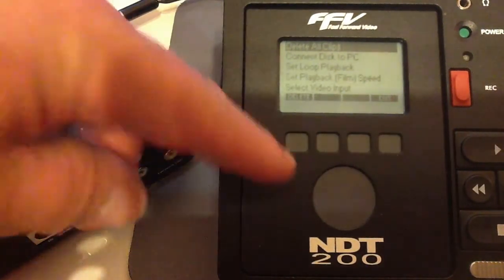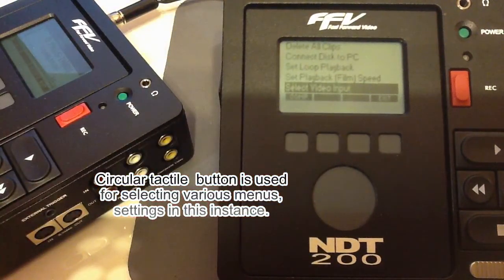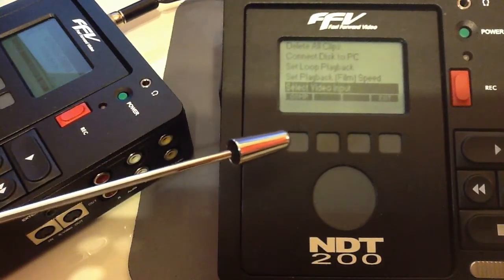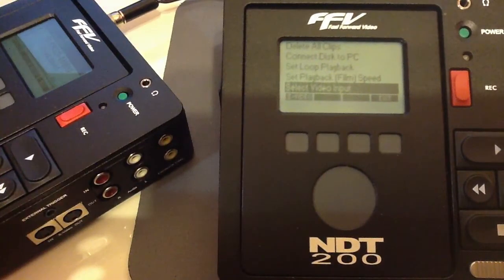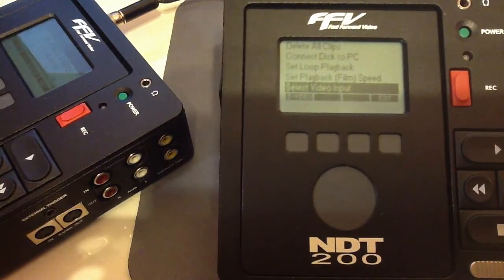By that I mean that, for instance, if I use the scrub button and go to the select video input, you'll notice that it says COMP for composite. What that means is that if I press the soft button here, I will select the composite input. Currently, the machine is in S-Video. So if I press here, the next input or signal will say S-Video, which means that effectively now the machine is receiving a composite signal and the S-Video is available for selection. So if I select it, then what I read is composite. So it's important to understand that when there is a toggle selection, what is being displayed is the next selection,